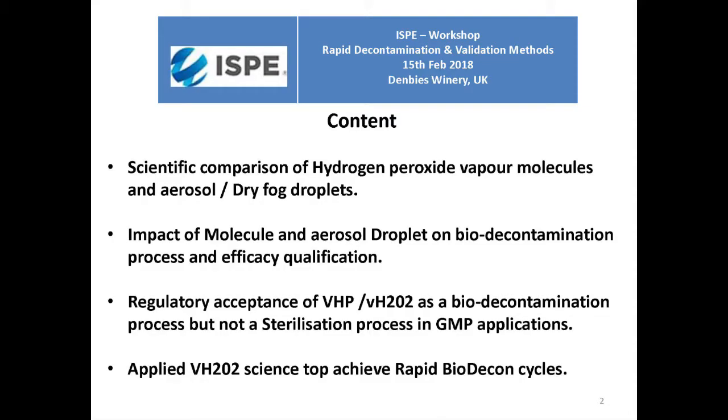Regarding the regulatory acceptance of VHP for biodecontamination of stopper contact surfaces as a sterilization process, there's been a step change last year when regulators started to up the ante on challenging the industry to understand more about the science of this process, and in doing so, not accepting VHP as a sterilization process or even H2O2 as a sterilant. That's their starting position. Industry, you respond by giving us a scientific understanding and the rationales to apply in your particular processes.